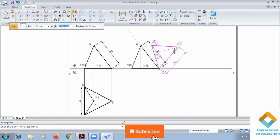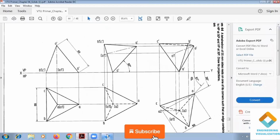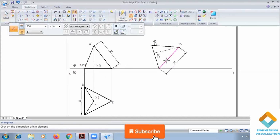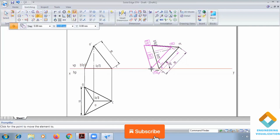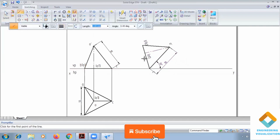So for this base edge, the angle is 50 degrees. Yes, this is the angle we get. You follow this procedure. Now project it downwards to complete the second position top view.